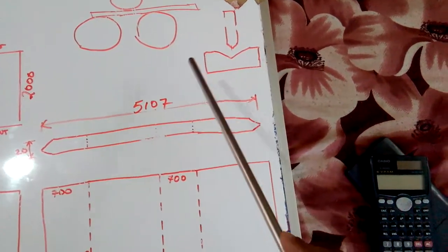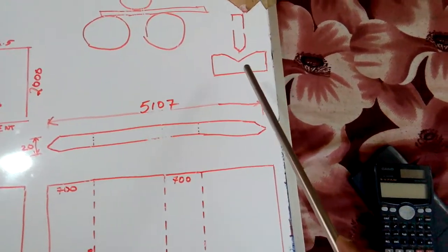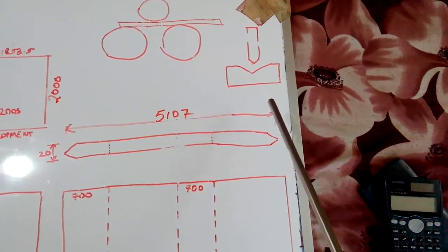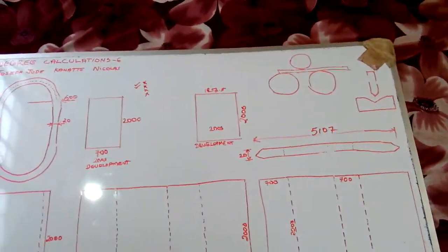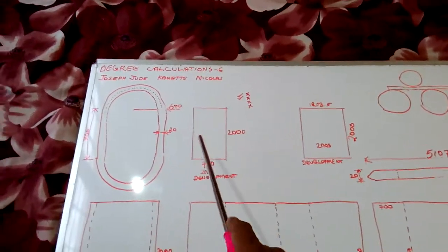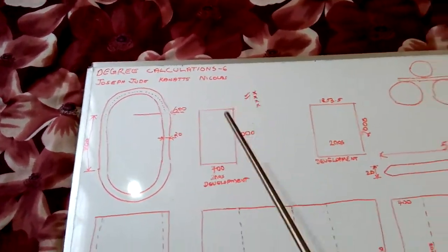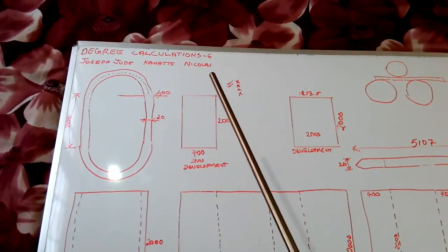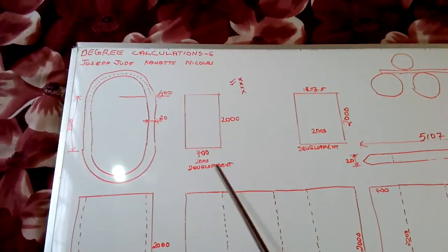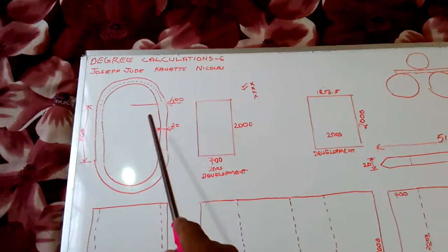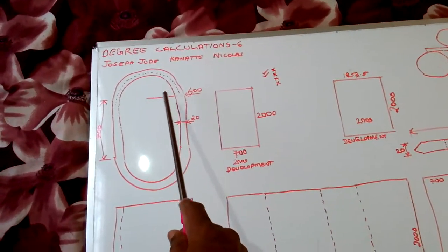Again we have to pull it, and again give a slight bending, and we can check whether it has a radius of outer diameter 600. For checking we have to make one template. With the template, we can check it from inside. That is the best way.